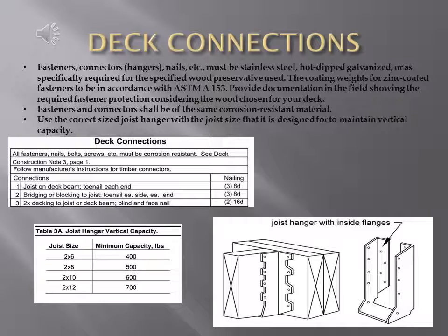Fasteners and connectors. Fasteners and connectors, also known as hangers, nails, etc., must be stainless steel, hot-dip galvanized, or as specifically required for the specified wood preservatives used.